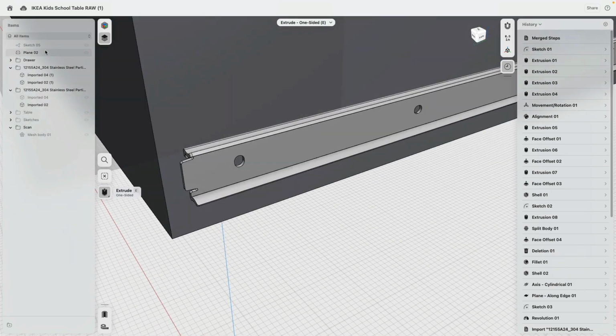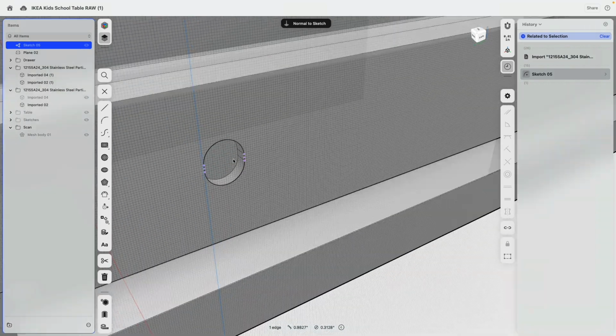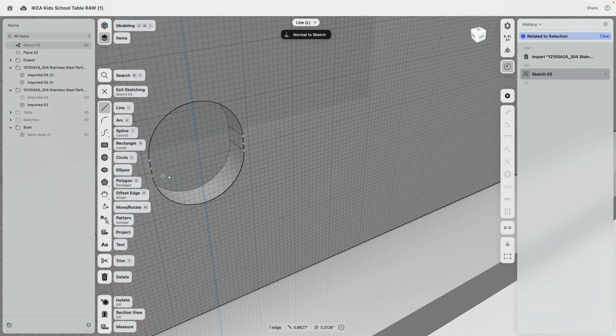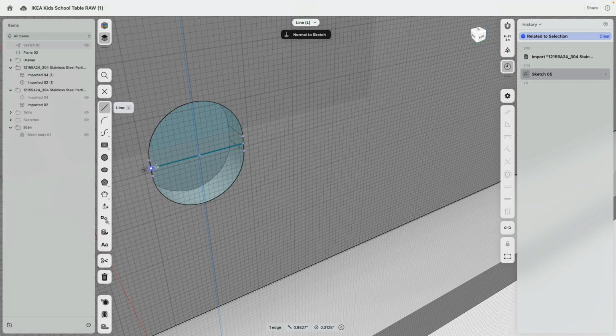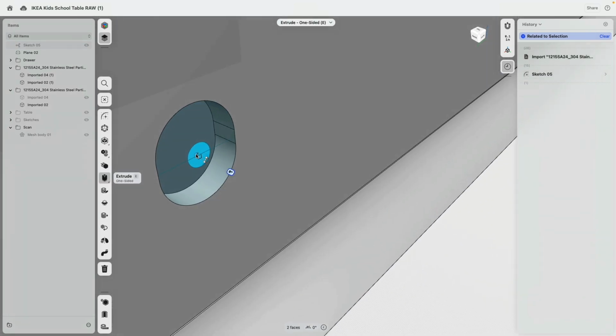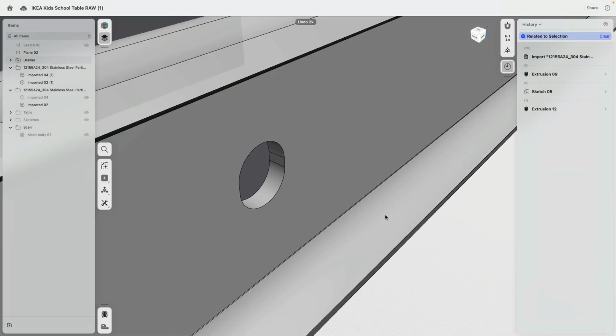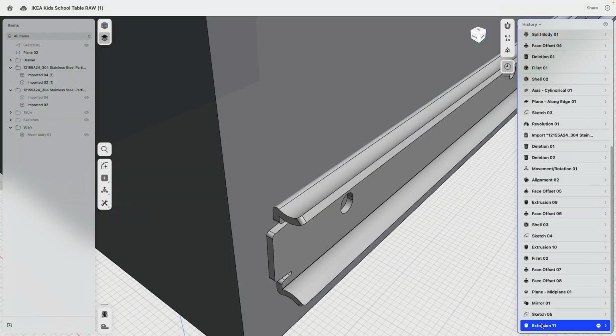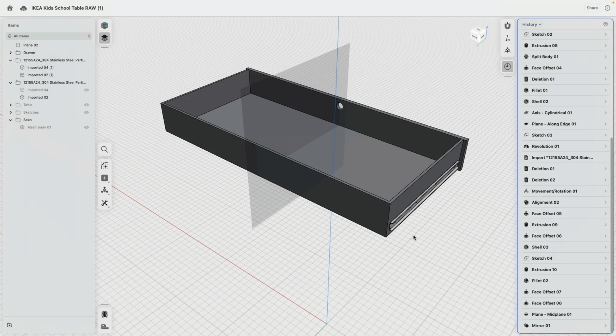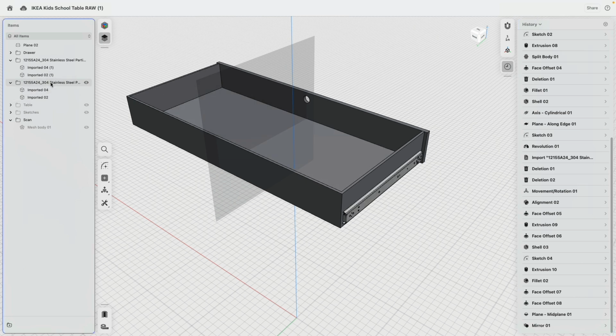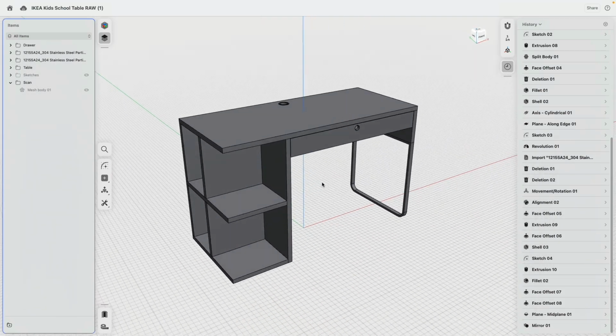Now, if I go back to this sketch, you see here, this is actually a vertical slot. So here I would just draw a line that's at the center. And then here I can draw the circle for the pilot hole and then model that pilot hole. Okay. In our design here, I will select these two steps and remove them because this was more like a demonstration, so you understand how this can be used later. And we are actually done.